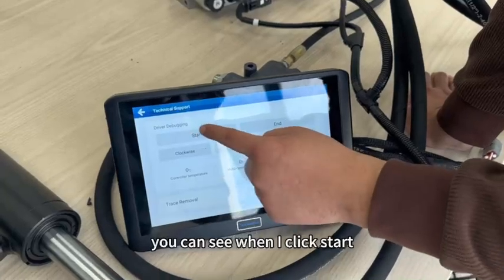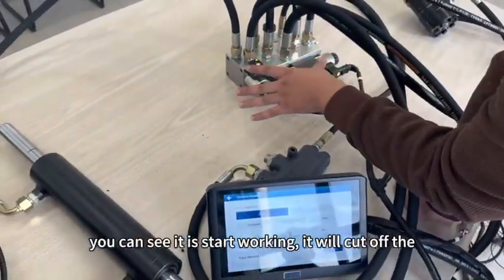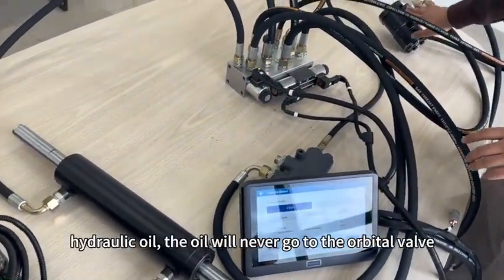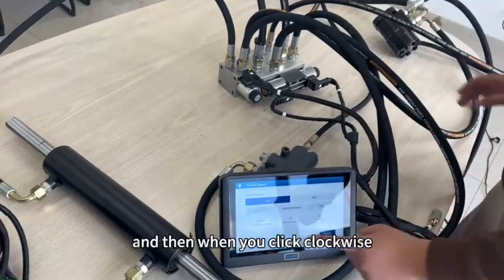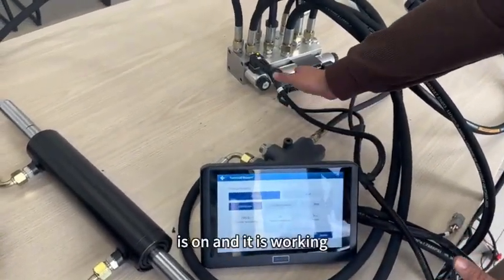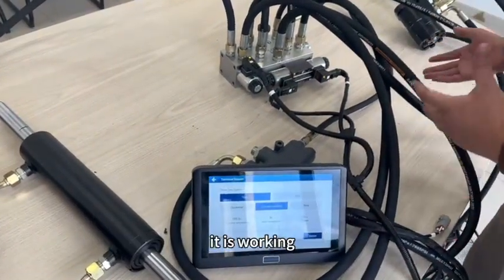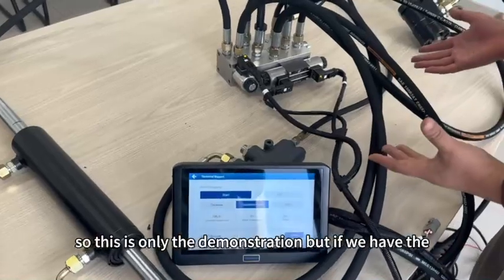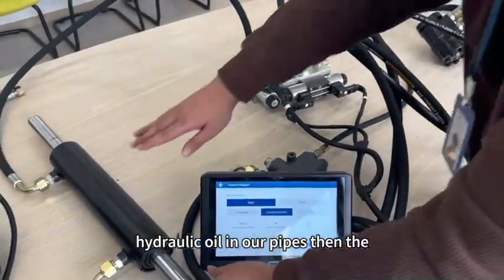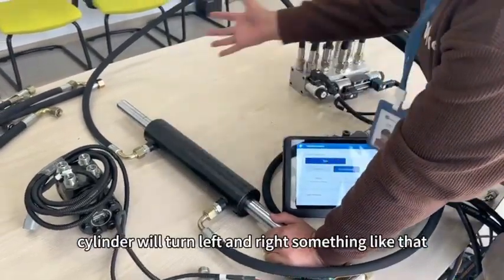So you can see when I click start, okay, the light of the cutoff valve started working. It will cut off the hydraulic oil. The oil will never go to the orbital valve when you're using the auto mode. And then when we click clockwise, this light is on and it is working. When we click counterclockwise, this light is on and it is working. So this is only the demonstration, but if we have hydraulic oil in our cables, then the steering cylinder will turn left and right and something like that.